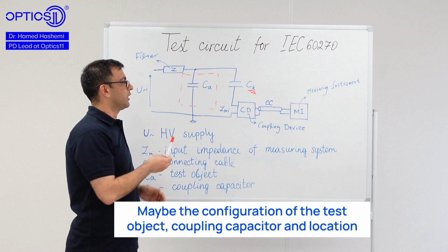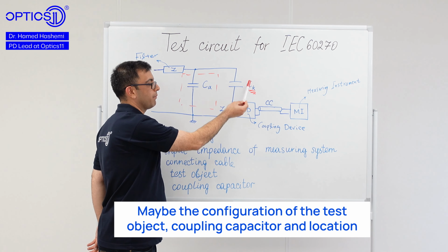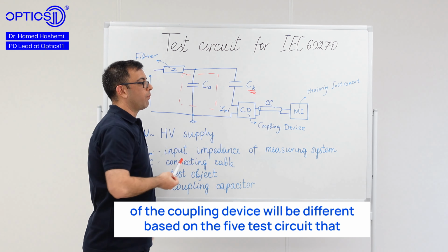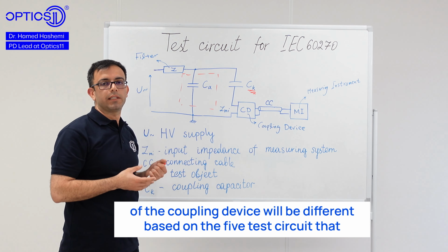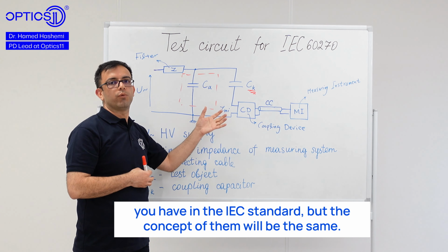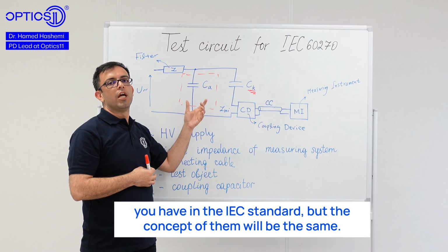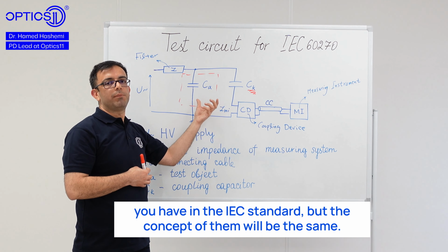Maybe the configuration of the test object, coupling capacitor, and location of the coupling device will be different based on the 5 test circuits in the IEC standard, but the concept of them will be the same.